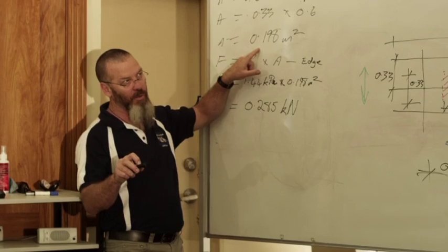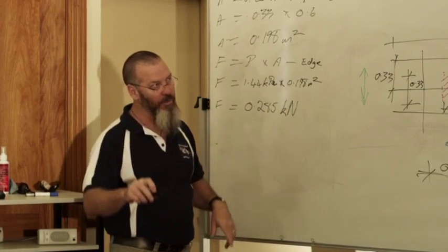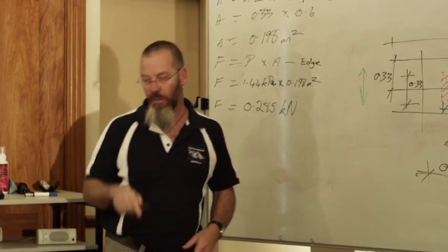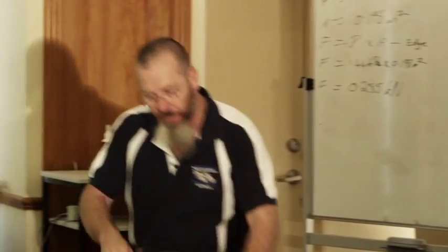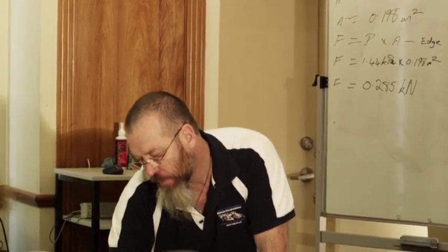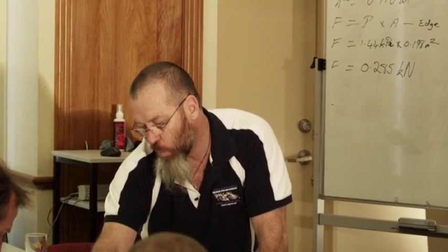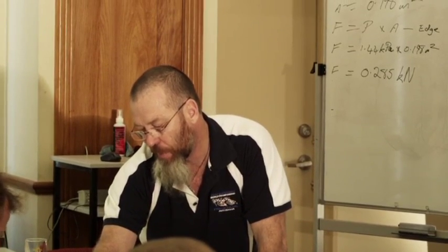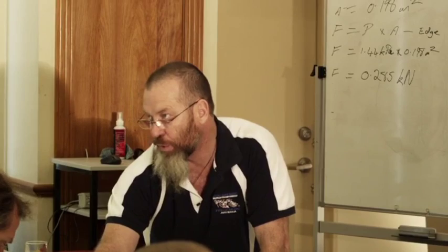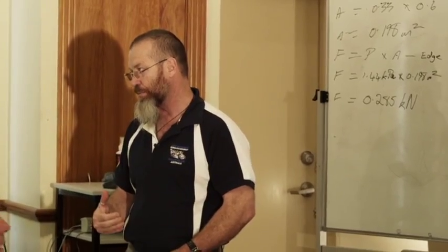Multiply that out, it comes to 0.11. On table 9.5 in type B, when you start at the top, here, you'll see that 175 by 3.05 plain shank nail equals 0.21 of a kilonewton of resistance. Okay? So that's the actual process that you go through.